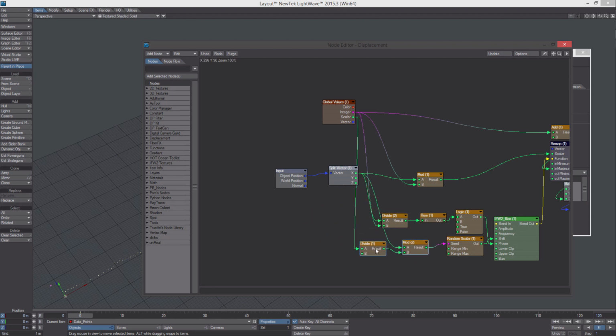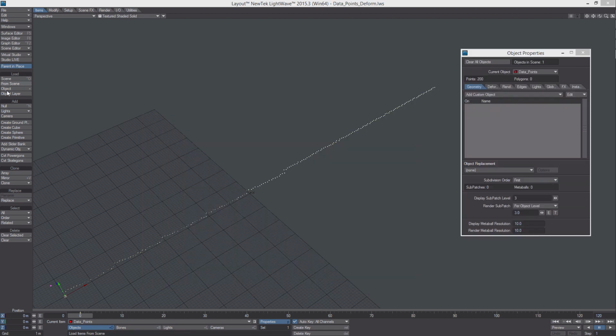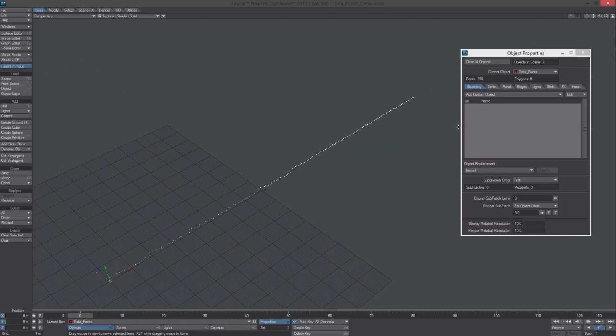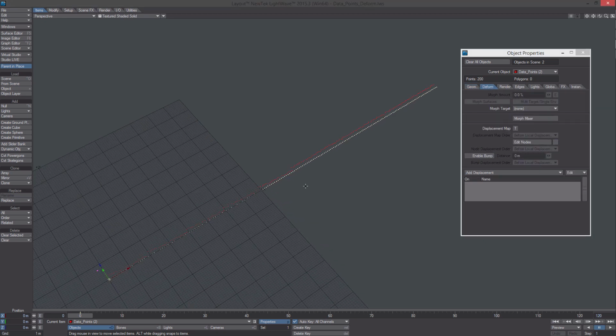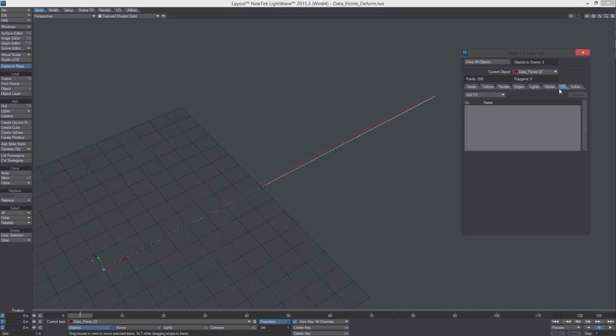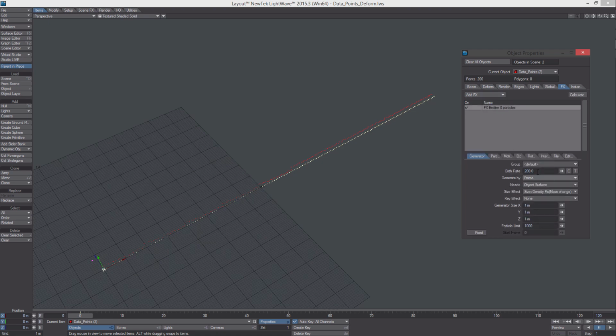So for the next part of this, what we're going to want to do here is create a particle. So I'm going to clone this object. Then I'm going to turn the deformations off for it. And then we're going to add an emitter to it. Add emitter, 200. We want to have the same number of points by the frame on the vertices. Size no change. Particle limit 200. Fix that. The negative stack count basically, so negative 20. That'll cause all the calculations to be done before frame 0.